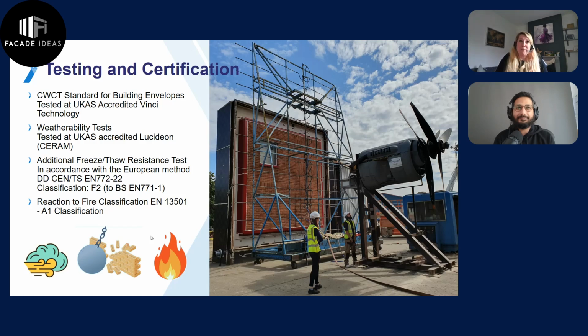So the system's fully accredited, so fully tested and certified under CWCT, tested at Lucideon, and also at Warrington for reaction to fire as well. And we have an A1 rated classification for this particular system. I will say when you're specifying brick face cladding systems, or any system for that matter, especially in the UK, please do check the classification that you have, particularly for fire, but also ensure that it is certified and accredited.